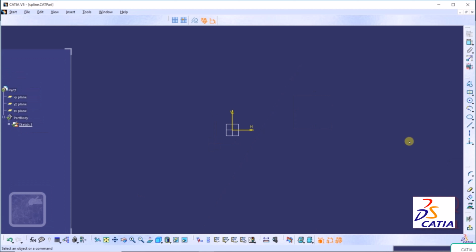Hello friends, in this lecture we will learn about Smart Pick or automatic aligning in the sketch mode. Whenever we draw any sketch in CATIA, the software will automatically try to find the references. To understand it in more depth, let's draw a line. I go to the line option and draw a line like this from a first point to a second point. Now we have drawn a first line. The software will try to take the references of this line when we draw more sketch.